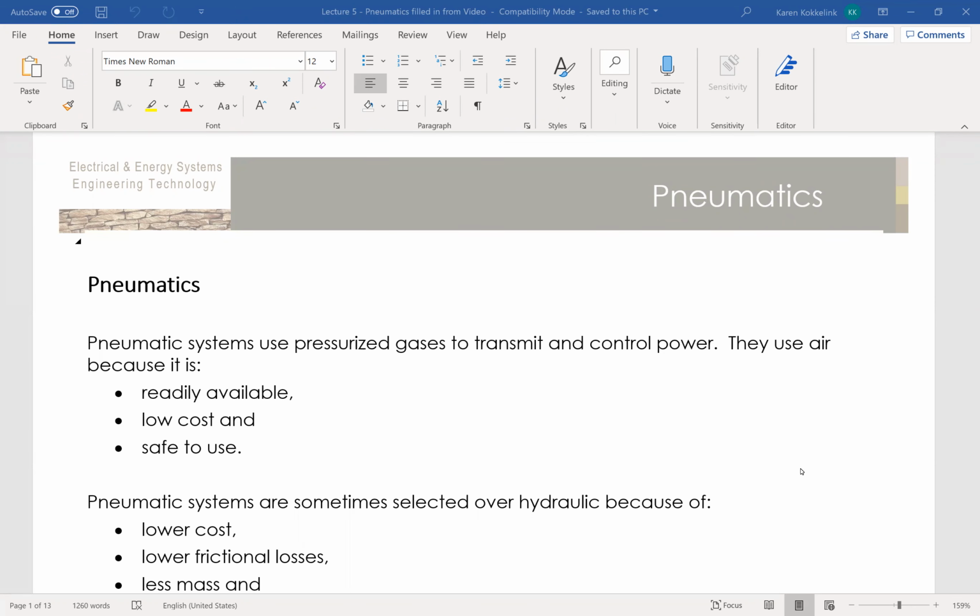So this will be a short video just to introduce you to the lecture that focuses on pneumatics. So far we've talked about fluid power systems where, again, fluids do not create power, but they transmit power. We've talked a lot about hydraulic systems where we can readily calculate the force over a cross-sectional area of a piston that has a pressurized fluid on the side. So we can put a force in one side and we can get a different force out the other side according to a ratio of the pistons.